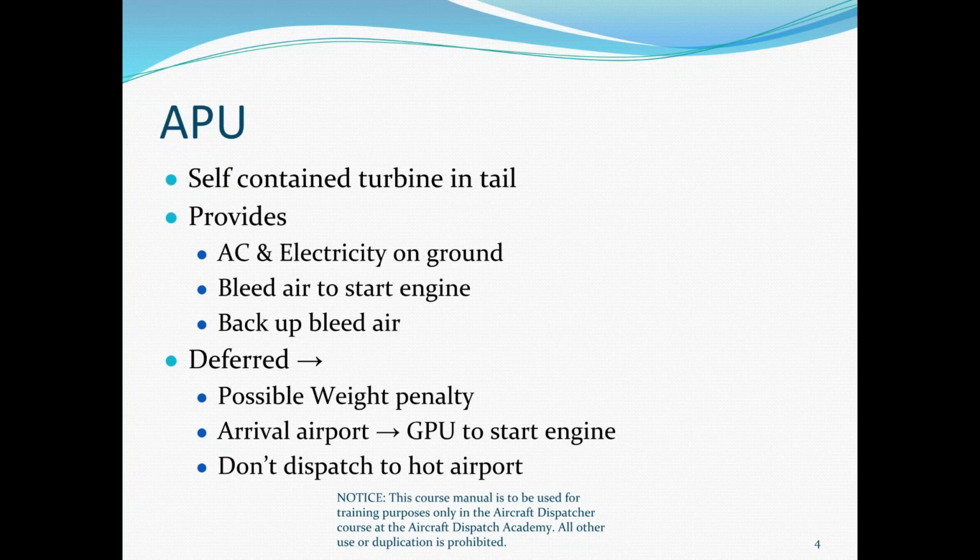The air's thinner. Already have the potential for a weight restriction. When you couple that with a weight restriction at a hot airport, it might leave you with like 3 passengers. Yeah, so that's one of the big ones, right? Could take a huge weight penalty at a hot and high airport. Remember, engines don't like hot and high.